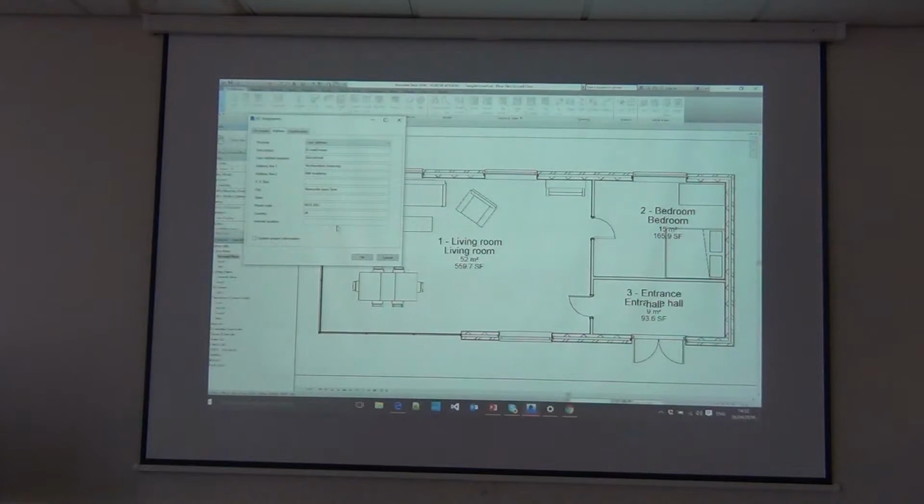There's address information, and this tends to be really about the site. Okay, so this is the project address details. So it's very specific to the project. And you can see at the bottom, if I tick update project information, what that does is that writes it back into Revit so you don't have to do it again. They store it in some hidden things inside Revit.